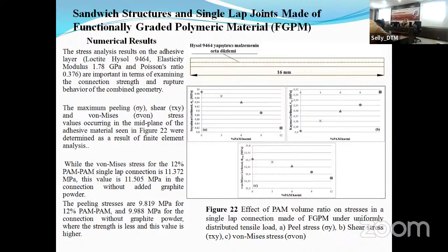In ANSYS, you can check the solution and the location, but sometimes we have a specific region, so we can create a path. Do you know that? We create a path by selecting the nodes. We define the path.